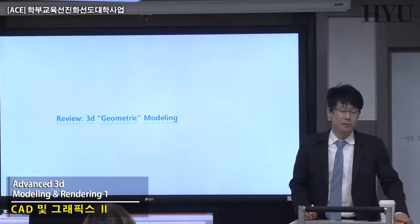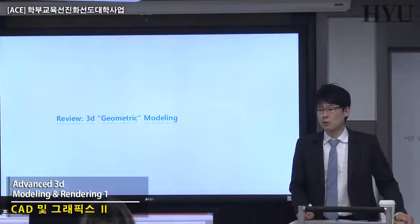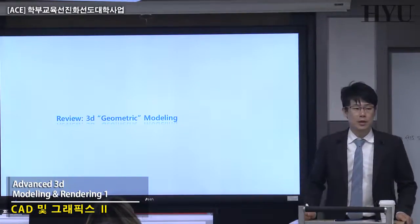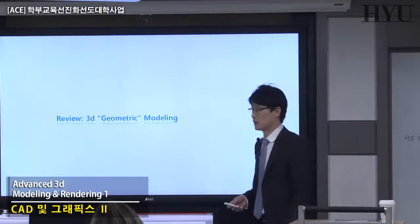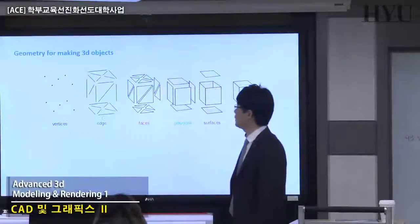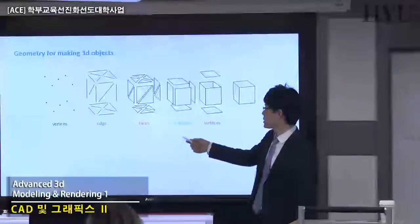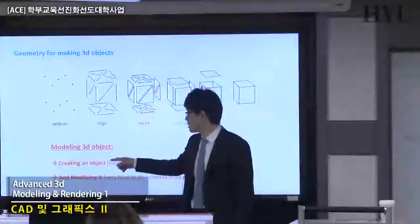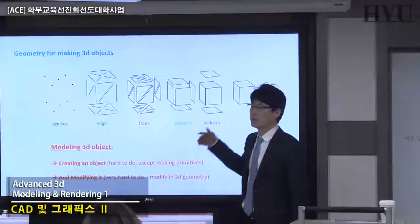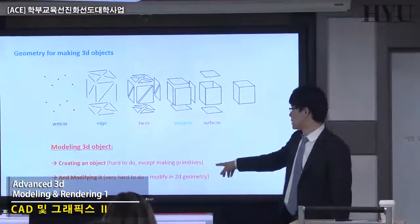So in terms of geometric modeling, let's review quickly, and I'm going to introduce you to today's lab exercise number 4. In terms of geometric modeling, how to quickly visualize your design thanks to what you have learned: 3D Max modeling, 3D Max rendering techniques, okay? So, geometric modeling. Here are the subcomponents of geometry: vertex, edge, face, polygon, surface. So modeling a 3D object means creating an object in terms of geometry, such as this kind of box shape. This box is one of the primitives, okay?